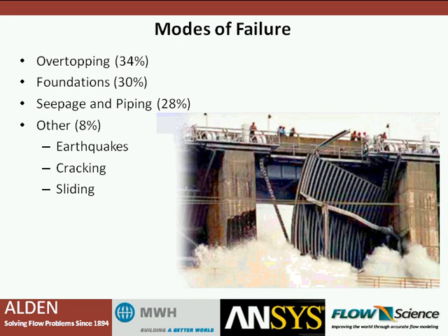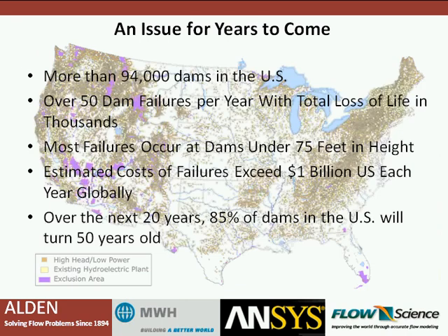Also, there are things like settlement of dam crests that can lead to having less available capacity in the reservoir, and thus a certain design flood may come and overtop the dam as well. So overtopping and spillway capacity issues are very important when it comes to dam failures.